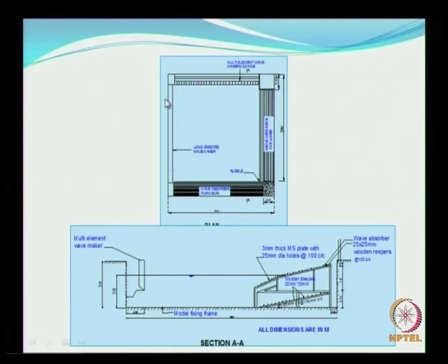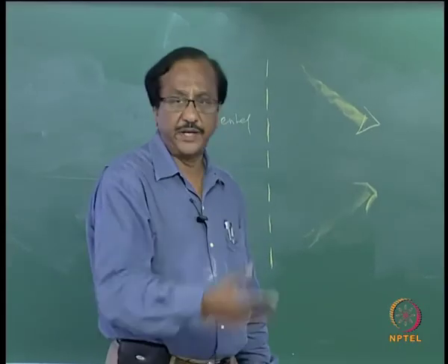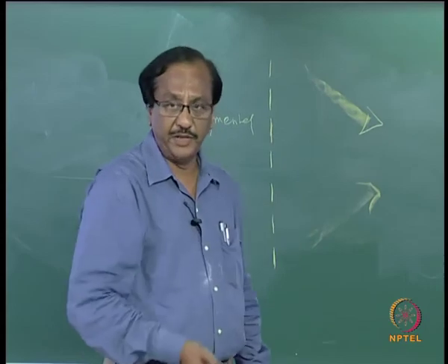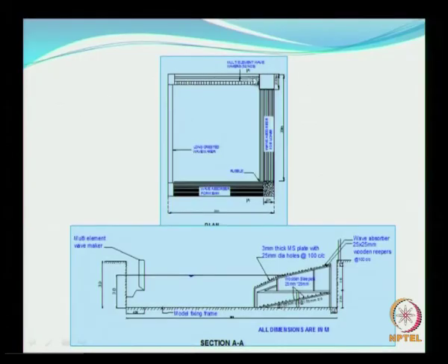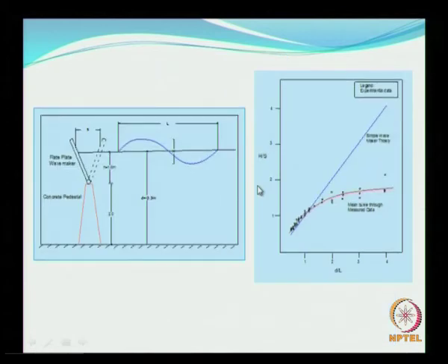It is better to avoid waves being generated in this direction, because this is a vertical wall that can give you reflected waves. So normally it is not preferred, we do not generate waves approaching in this direction, but we can always generate waves moving in this direction, because these two wave makers can take care of the absorption.